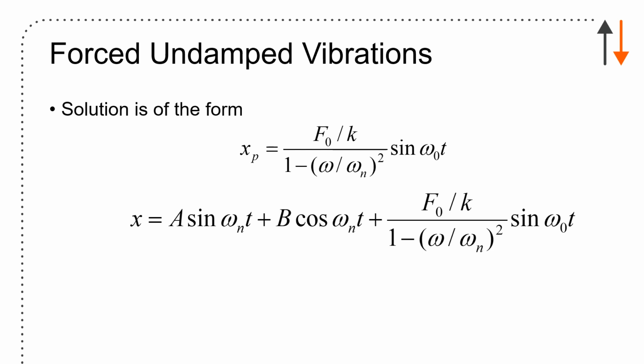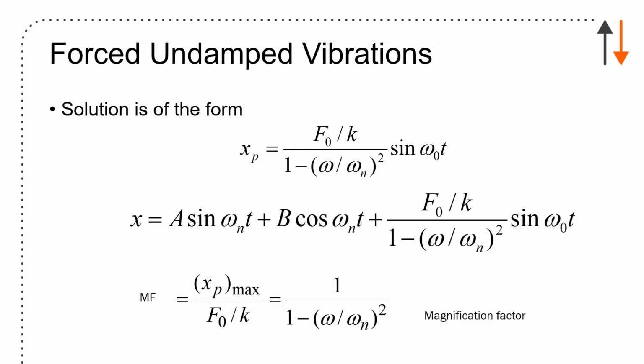And it would shake apart at that frequency associated with the forcing frequency, which might be, for example, if you're driving the 401, bumps on the road. So that magnification factor is 1 over 1 minus omega squared over omega n squared, and it's something that people look at, especially when they're trying to do various types of analyses. So for example, I have a set of aerodynamic control experiments, and I actually try to operate the control devices very close to a resonance frequency or a magnification factor, so that I achieve very high energy outputs from these devices.